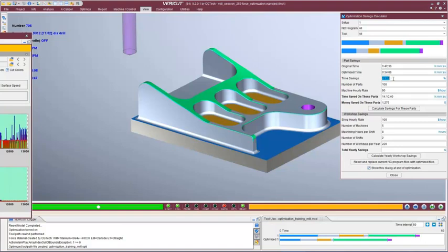Nearly 20% savings on a program, remind you, that was an optimized type of a program out of a high-end CAM system. That's quite a bit, but normally you'll see more. If you optimize just an average NC program that you have in your shop, you typically will see 25 to 45% savings, even in hard metal parts like titanium.